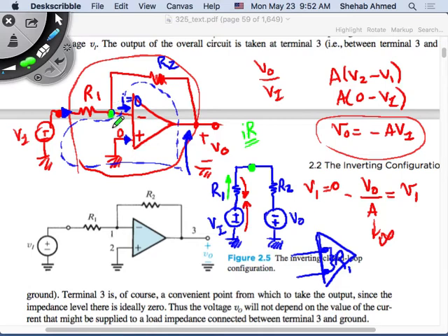Feedback made the voltage between these two nodes 0. There's no voltage difference between them. So these two nodes, they track each other. And if I made R2 0, it's so easy to do that with a small voltage. How about if I put a value for R2? Then I have to play with this V to make sure that I push enough current to bring down this voltage to a small value. With or without R2, R2 small or big, it's a different story, but at the end of the day, I can do that.